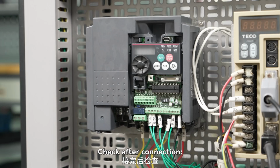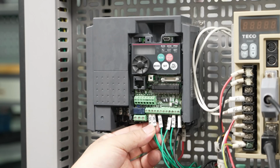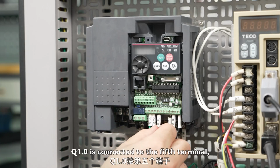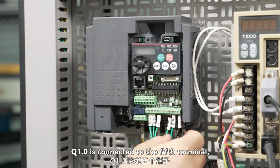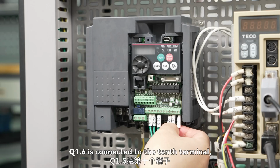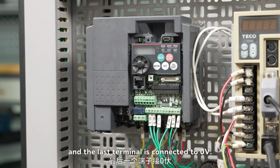Check after connection. Q0.5 is connected to the second terminal. Q0.6 is connected to the third terminal. Q1.0 is connected to the fifth terminal. Q0.4 is connected to the ninth terminal. Q1.6 is connected to the 10th terminal. And the last terminal is connected to 0 volt.